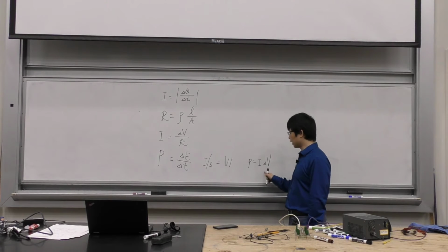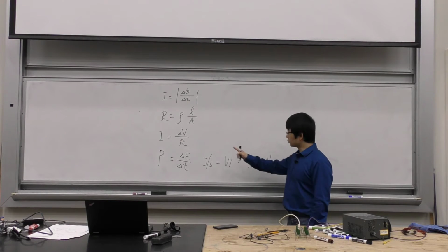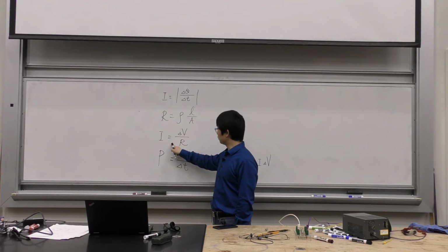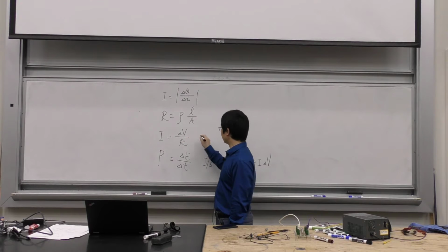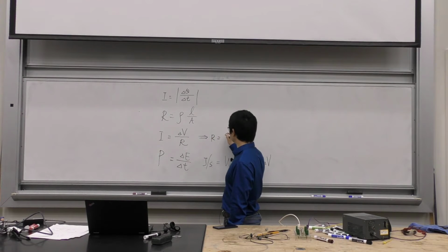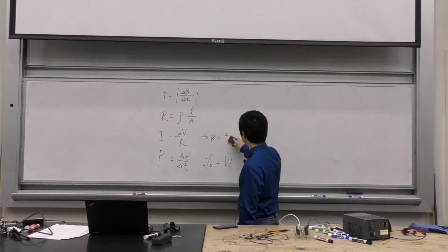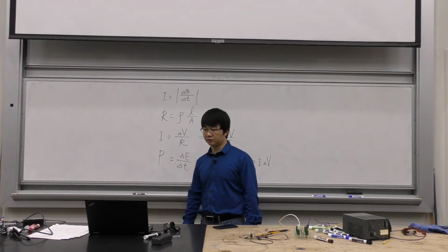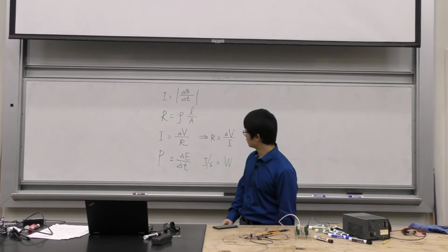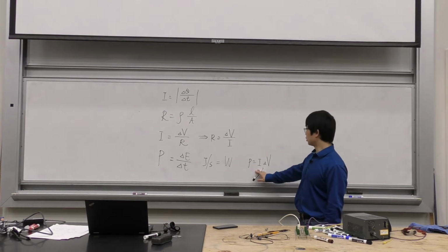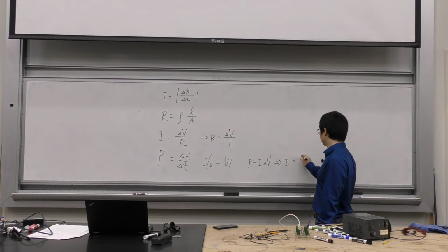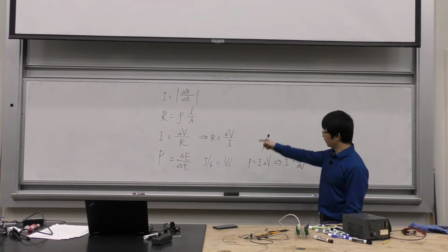So I can divide both sides to find the, no, I'm sorry. We want the resistance. But if we want to find the resistance, we can just use Ohm's law by doing voltage divided by current. We know the voltage, if it's connected to 110 volts, the power of this hair dryer is going to be 1300 watts. But we don't know the current. Well, that's how you calculate the current, right? You can rewrite this equation, find the current, and then plug it into Ohm's law.